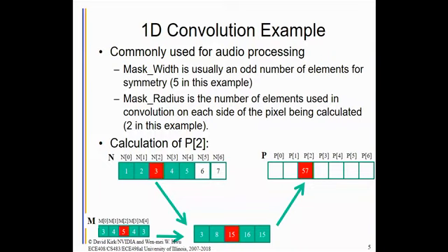So we need to somehow figure out a way to reduce the number of samples to be able to process them in a feasible way. And convolution is definitely an important technique for us to reduce the number of degrees of freedom and have feasible algorithms to process these signals. So we will define a mask width. The mask width is essentially the number of elements, including the element itself, involved in the generation of an output value, right?